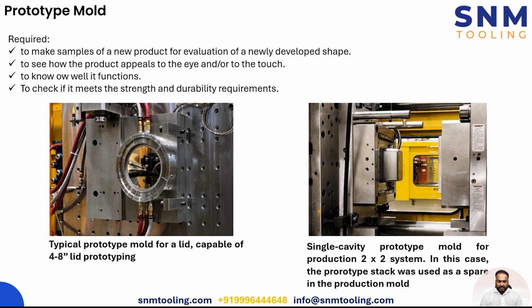a production mold, right? Now, if there are different prototype molds which we need to make, instead of making a stack and plates for each of them, we can rather make a single mold shoe to accommodate different sizes of core and cavity inserts, right? So this is something which can be done to reduce the cost of the prototype mold.